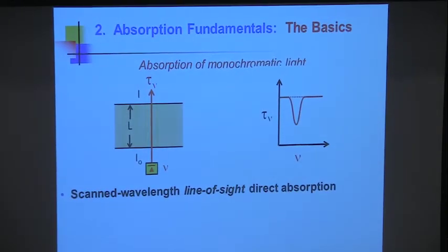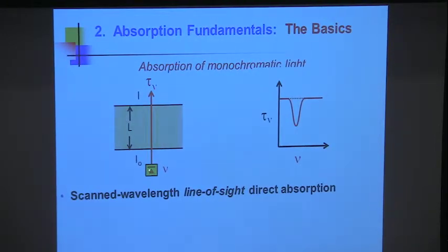What we're talking about is taking a laser source, usually a continuous wave or CW laser source, operating at some frequency nu or wavelength lambda, incident intensity I0, propagating it across the duct path length L and measuring the fraction of the transmitted light, where tau is the fractional transmission. So that's the ratio of the output transmission light to the input light, neglecting the windows. We assume usually that it's uniform along this path, and that's a deficiency in the theory, but that's what we have to do.